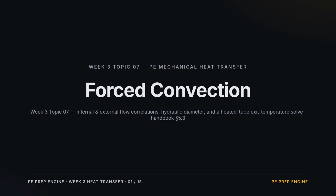Topic 7 of Week 3, Forced Convection. The Nusselt number correlations for flow inside a tube and over a flat plate, the hydraulic diameter for non-circular ducts, and a worked solve for the exit temperature of water in a heated tube.